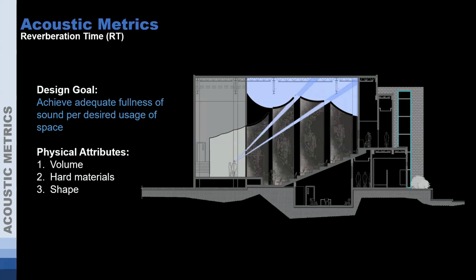But we may have a performance hall or other space, maybe a religious facility or house of worship, where a longer reverberation time is desired. They don't want it to be so acoustically dead. So we might be looking at 1.2 or 1.5 seconds for something like that, even 2 seconds. You may even get it a little higher if they're doing something like Gregorian chants. If that's the focus of a space, they may want a very long reverberation time for that specific sound. But then you have to watch out, because that may be good for Gregorian chants, but your spoken word may be a little different,